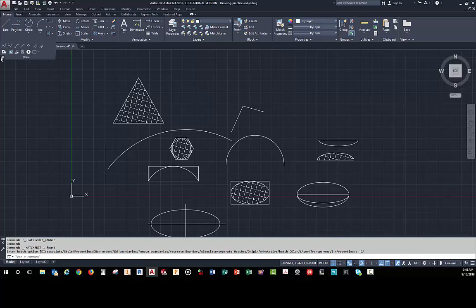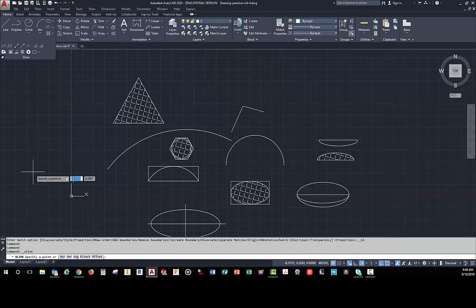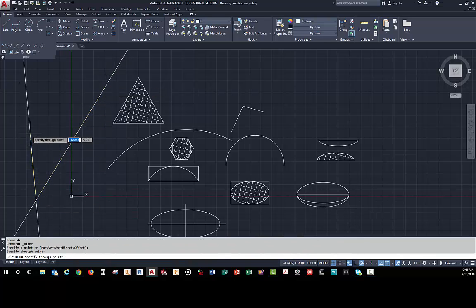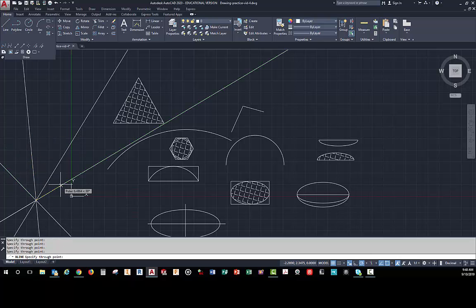Click on this, pin that down, okay. Alright, so you have spline fit, you have a spline CV, which is constant control vertices. Like I said, when I mentioned splines in the polyline, the fact is they don't go through the actual points you use for the most part. Then you have a thing called XLine, which is basically just an infinite line, right? Goes each direction. It is a true line. It goes on to infinity.